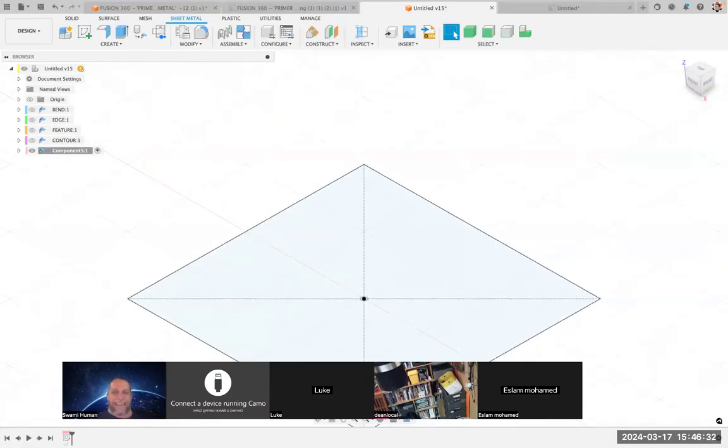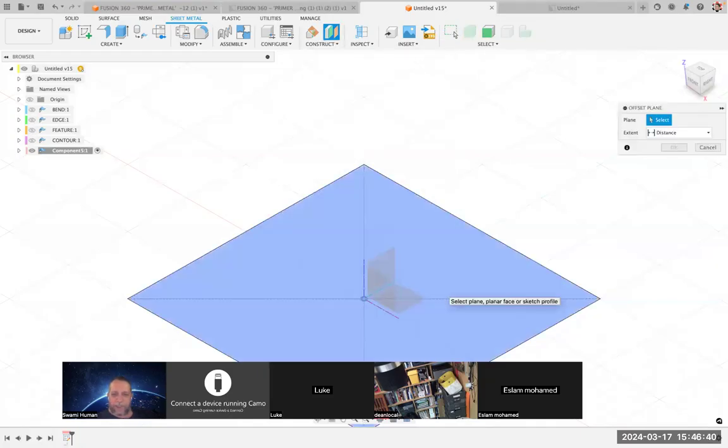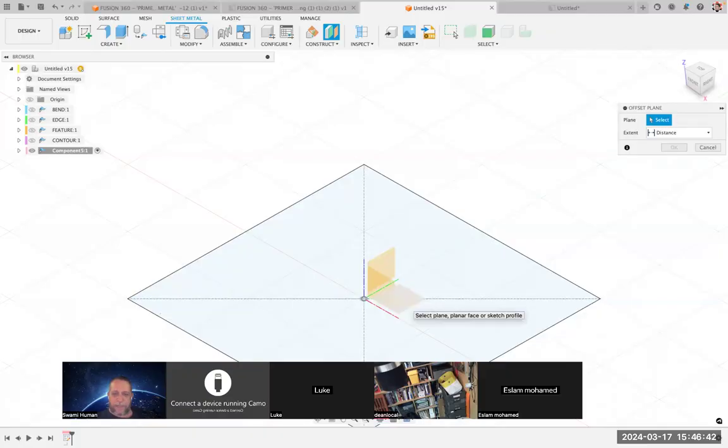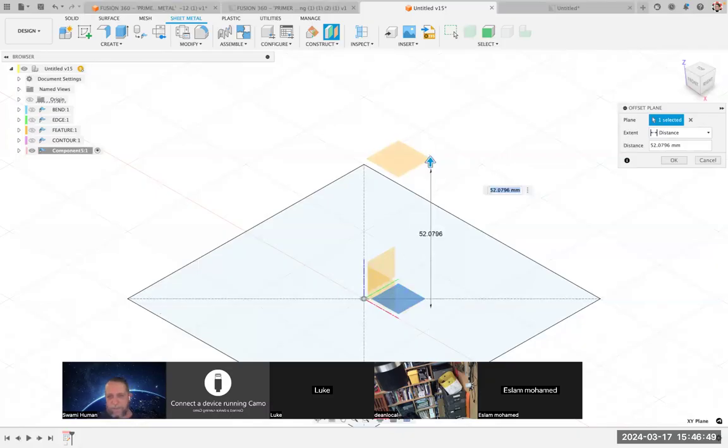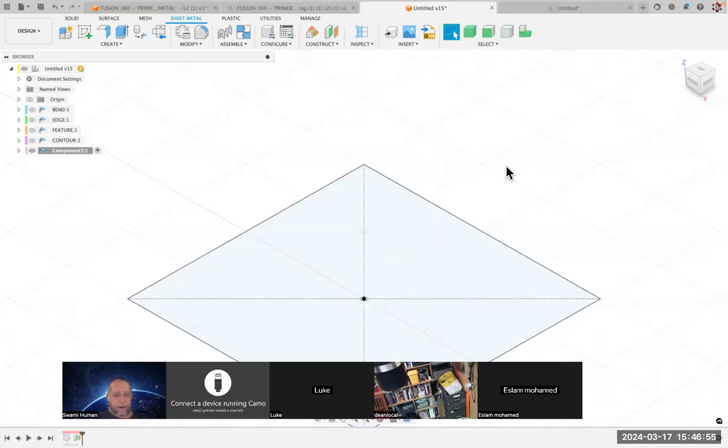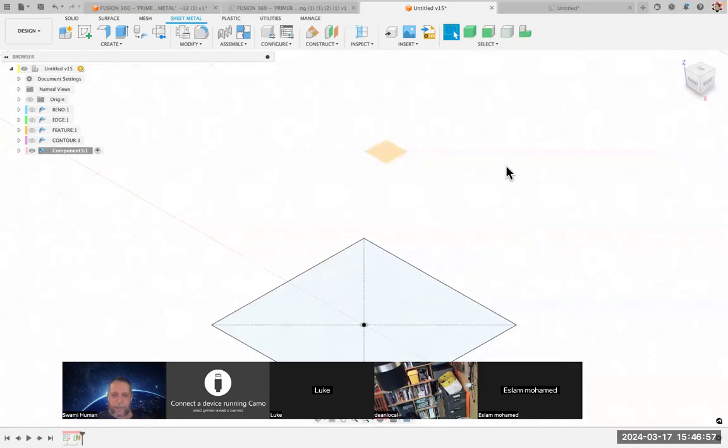Let's make an offset plane so we can do our circle up higher. So there is an icon, should be one there for offset plane. You can do it from the sketch or from the ground plane. Typically, the ground plane is probably better. And then this one can go up however high. Maybe it goes up 100. Like that. Alt double click, Option double click. There it is.